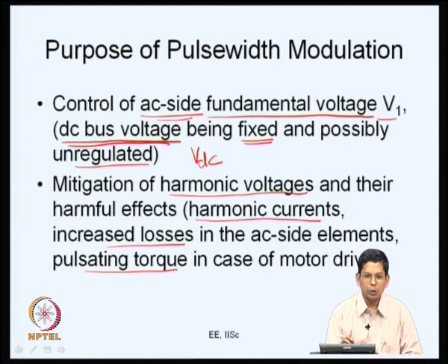And if you look at them through phasors, we will deal with all this at a later date in greater detail, but just to help you grab this, you have two fields, one pertaining to the stator and another pertaining to the rotor, which both revolve at the same frequency and they have a fixed phase angle. Because of the interaction between the two, you produce a steady torque.